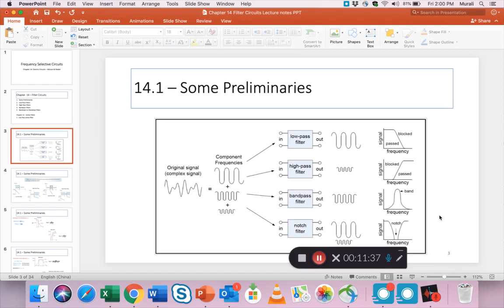The low pass filter, for example, has a high magnitude, a flat line, which is the response of the filter. Assuming a gain of 1, whatever comes in comes out, but only for input frequencies below the point where it starts to drop off. Everything below that has a gain of 1, but high frequencies, which still exist on the input, don't get a chance to go out.